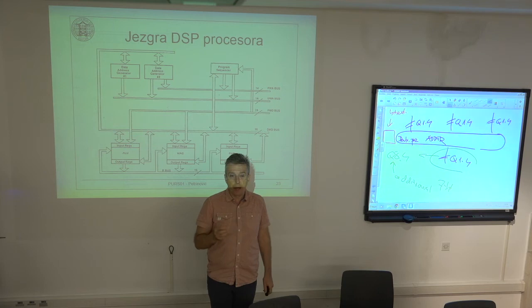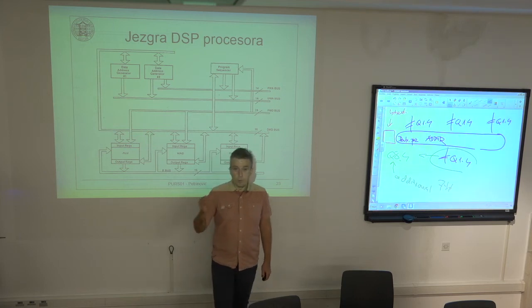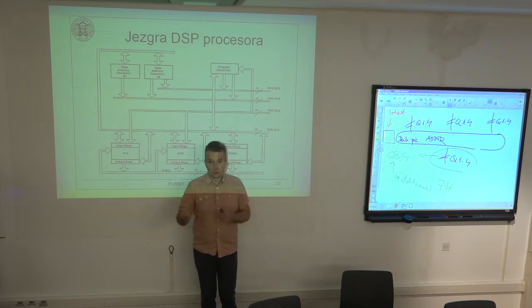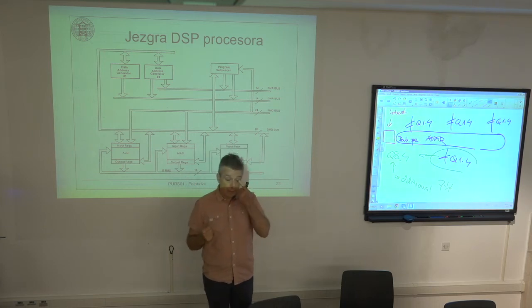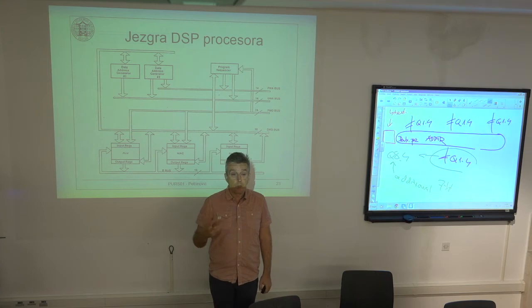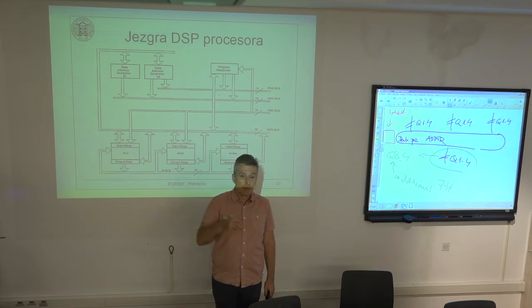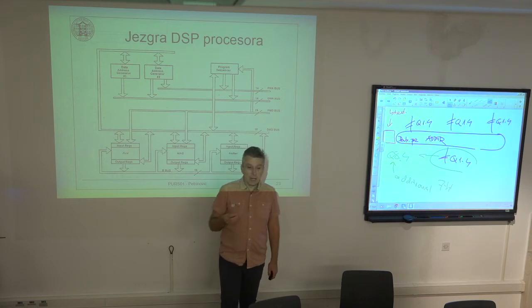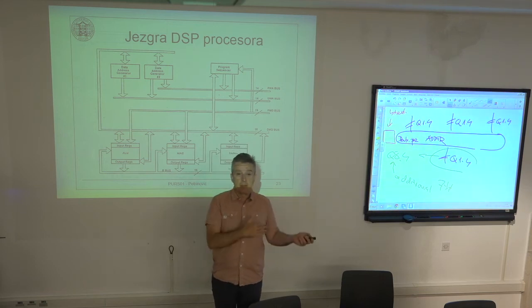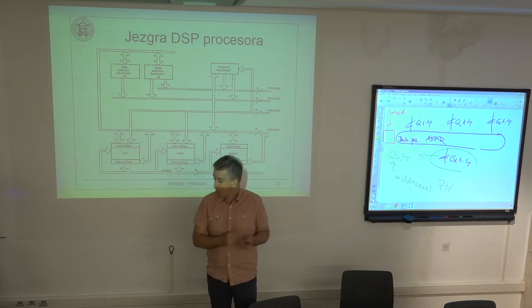So you can specify a large number of bit position shifts to the left or to the right, and all of this is executed in a single cycle. So it is not executed as 17 shifts by one, by one, by one. It is executed in a single cycle as shift by 17-bit positions to the left, for example.